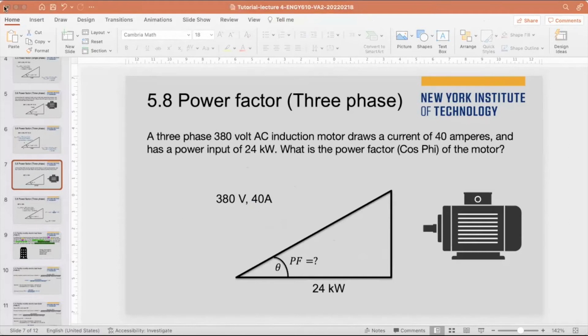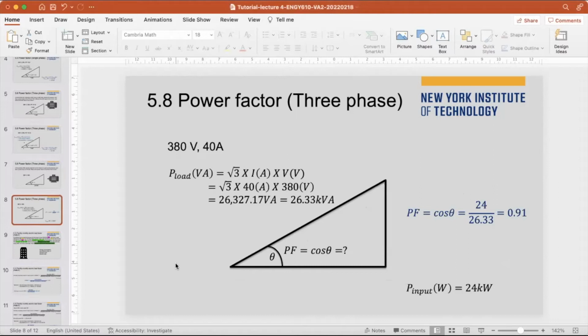And so with the same idea, we can tackle whatever value you want by the power triangle. So this time we know about the apparent power and also the real power. Then just by the same concept of the cosine, we can get the power factor. But for this question, I don't think I need to go into very much detail. Just by the simple concept, you need to construct the power triangle and put the numbers in the equation, and you can get the value.